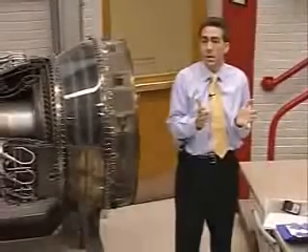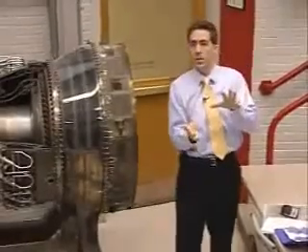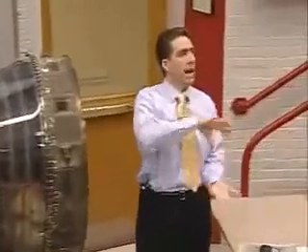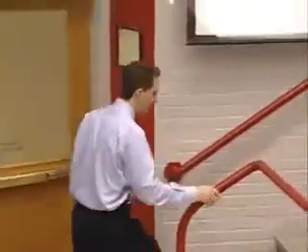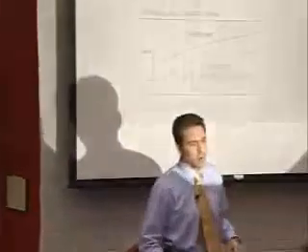And each time you're keeping the velocity pretty constant so that the axial component of kinetic energy through the machine is about the same. But you keep adding swirling components, convert that into internal. Add some more swirl, convert it to internal. Right? So let me put a few more words around that.